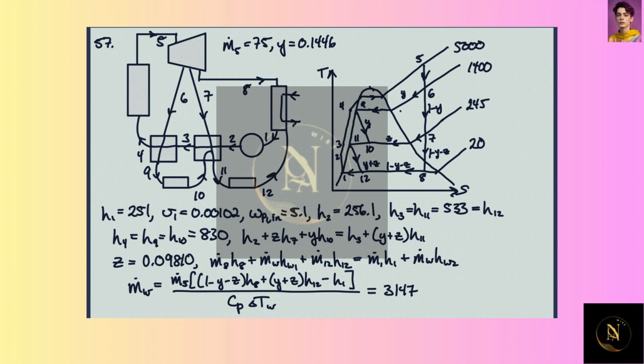So let's see here. Then we get the enthalpy at 8, 9, and 10. Okay, so then 4, 9, and 10. Because we know, at 4 we have a saturated liquid. And at 10, again, we're assuming that we're not having any changes there. This is kind of a line of constant enthalpy. And then at 4, it's also the same.